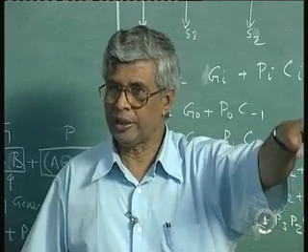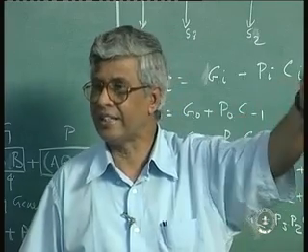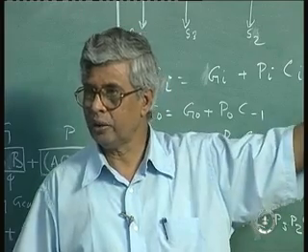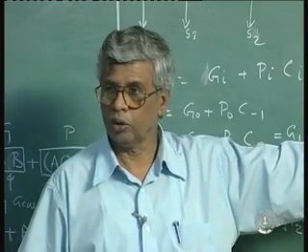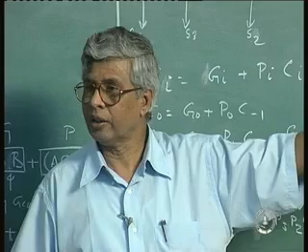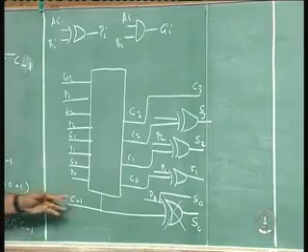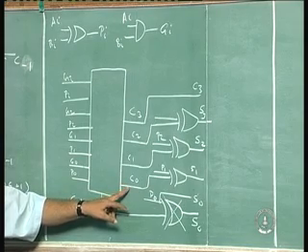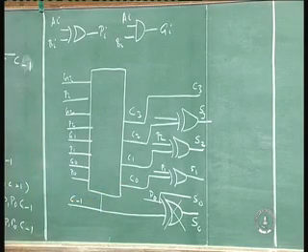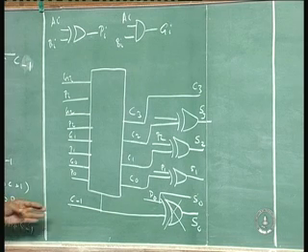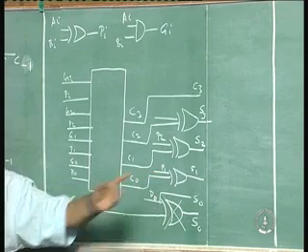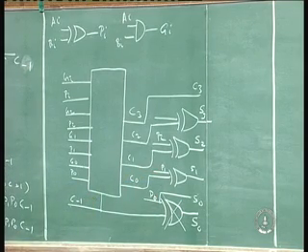So if we are talking of 8 bits or 16 bits or 32 bits, even for 4 bits, it is 8 stages in the ripple case. In this case it is 1, 2, 3, 4. Of course, some I have not taken into account there also. So here the carry is available after the 3rd stage itself. There the carry will be available after 8 stages, and some of course will be parallelly available. Here also, some will be available after 1 extra stage, some after 4 levels of gating, which is again faster by 4.